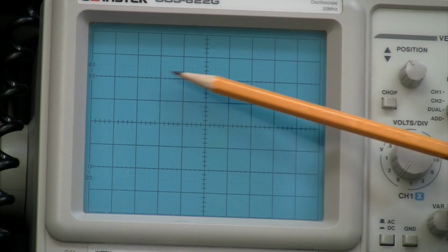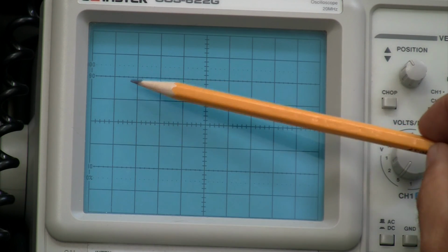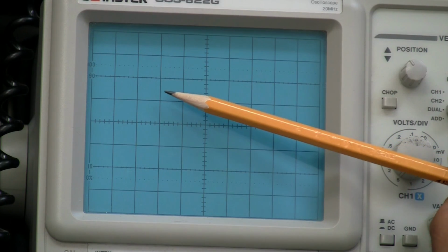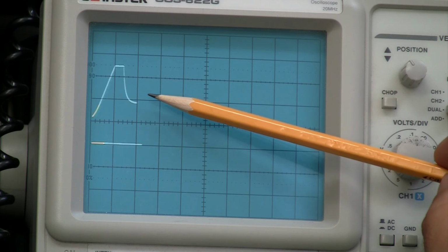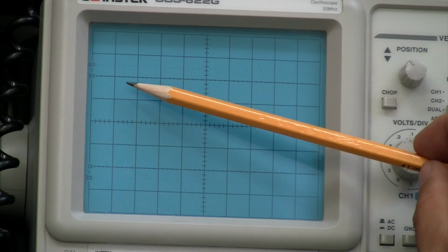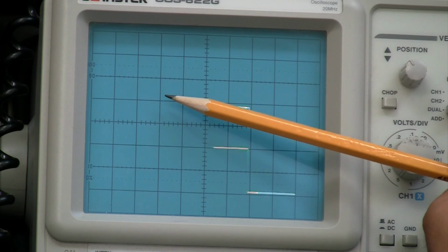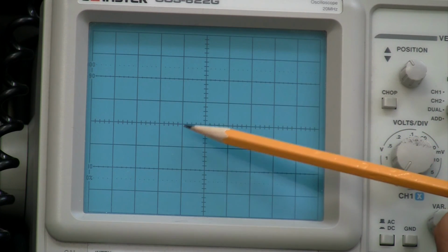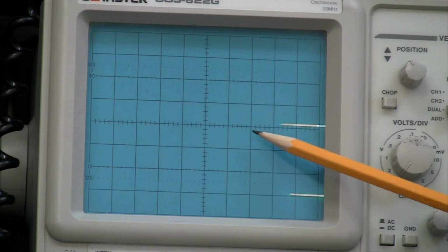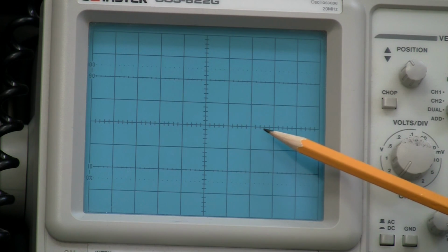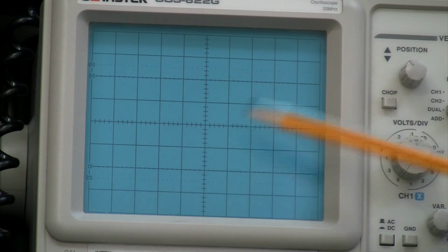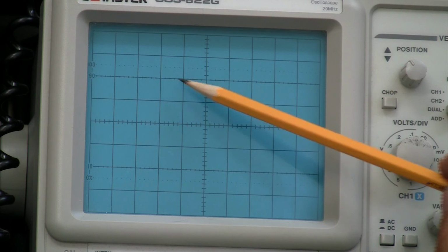If I want to move that hold segment to the left, I have to decrease the attack time of the envelope generator, which is very hard to do because it's set so fine. There we go. Now the decay time is also moving along with that, so these two depend on each other. I can increase the pulse width on the Q106, which will move this release time back, as you can see here. And by adjusting these knobs all together, I can essentially move this around a little bit.